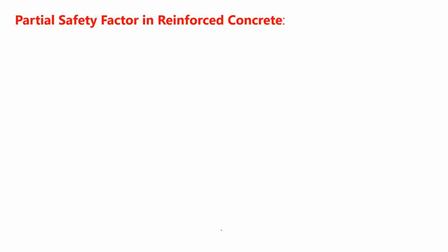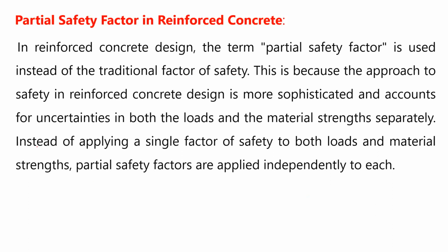Now partial safety factor in reinforced concrete. In reinforced concrete design, the term partial safety factor is used instead of the traditional factor of safety. This is because the approach of safety in reinforced concrete design is more sophisticated and accounts for uncertainties, and this is most important, uncertainties in both the loads and material.